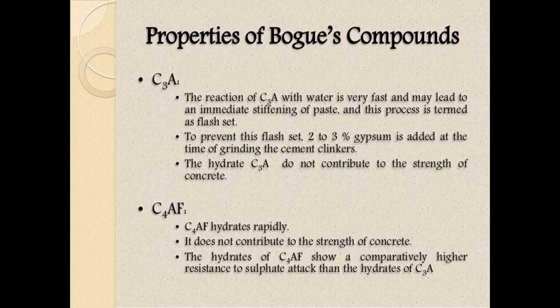It hydrates rapidly. It does not contribute to the strength of the concrete. The hydrate of C4AF shows a comparatively higher resistance to sulfate attack than the hydrate of C3A. So it does not contribute to the strength of the cement, nor is it responsible for the setting time of the cement. It has resistance to sulfate attack.